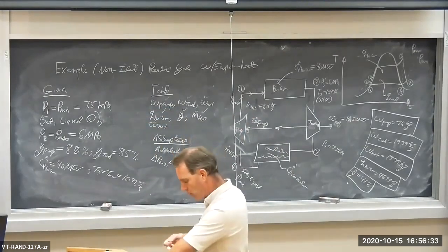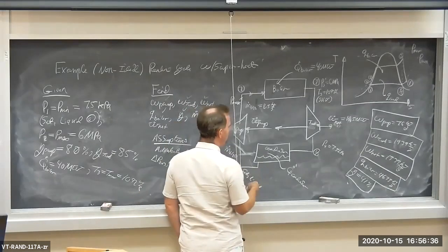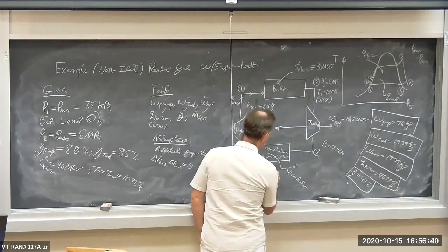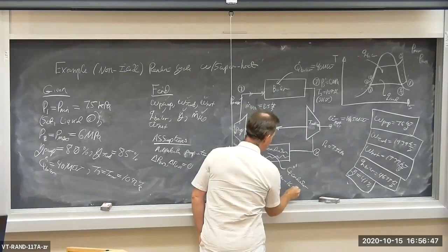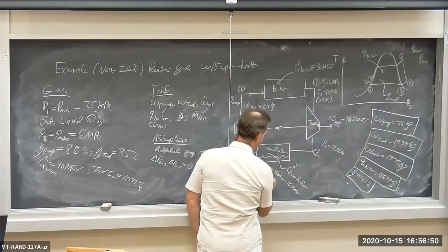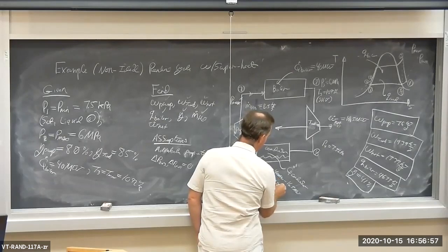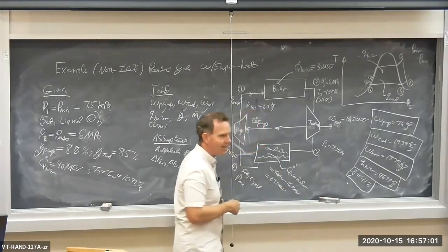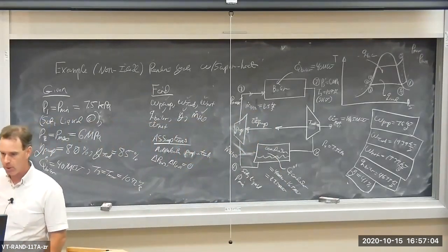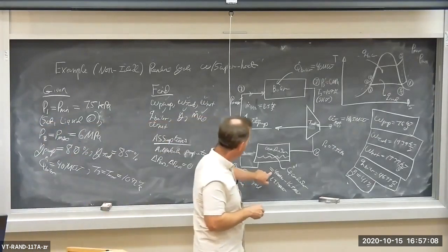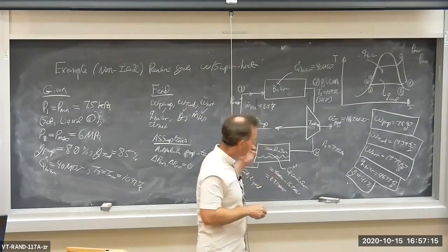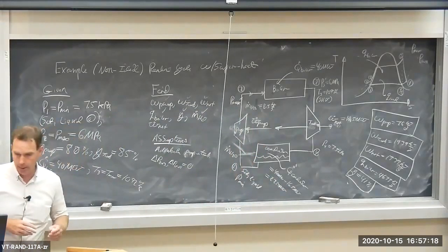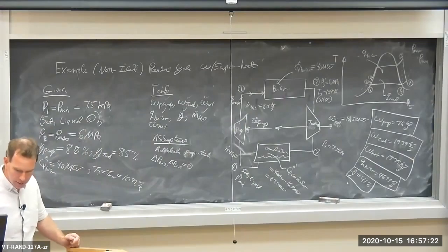16.5 megawatts comes out in the form of work. The rest of it is rejected. By the way, I can immediately calculate the condenser heat rejection. That's going to be 40 megawatts, what goes in, minus what goes out as work, 16.5 megawatts, which gives 23.5 megawatts. If you want to know what the heat rejection is at the condenser, it's 23.5 megawatts. Q dot boiler minus W dot net equals Q dot condenser, 40 minus 16.5, 23.5. I think that's right. All right, ladies and gentlemen, that's a fairly decent problem. Take care.